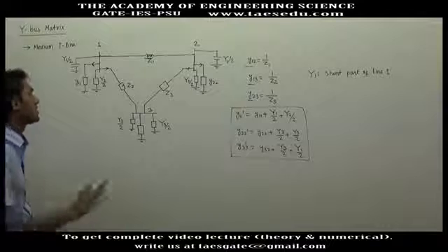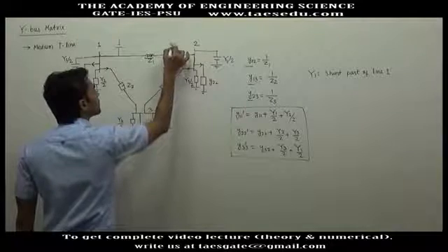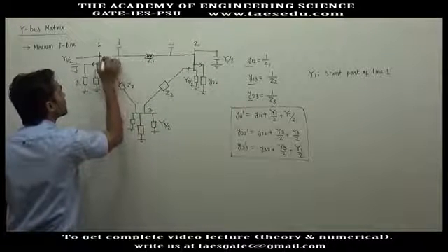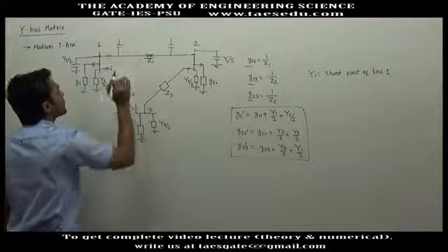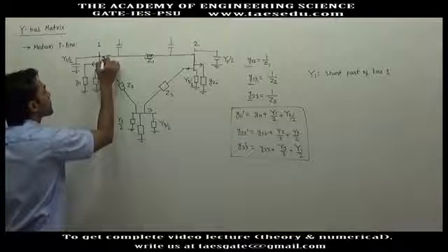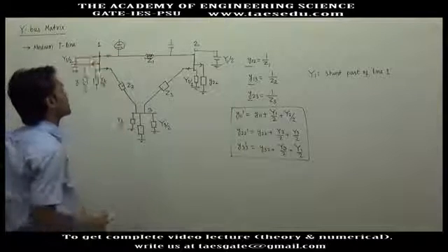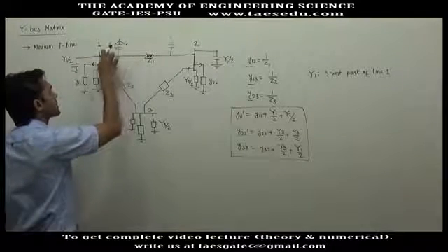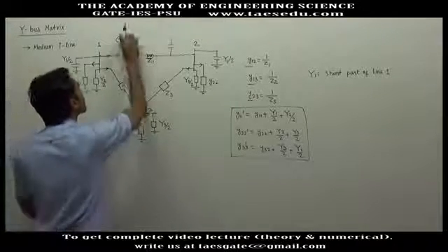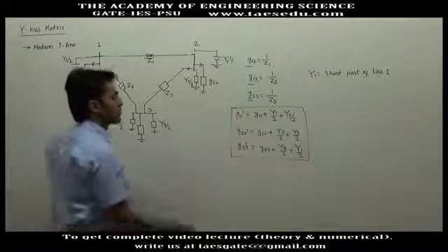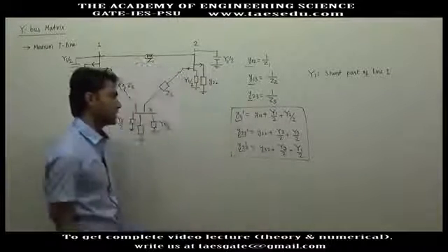If the shunt part was not connected at the extreme end, let's say the shunt part is connected here, there would be some impedance here also, and in that case we could not say that the shunt part of the line will act as the shunt part of the bus. But in the modeling, this is connected at the extreme end, and on the extreme end of the line you have the bus. So you have the new shunt elements. This way you can find the new admittance matrix.